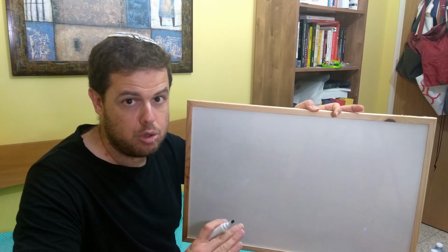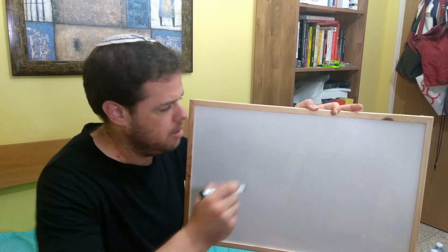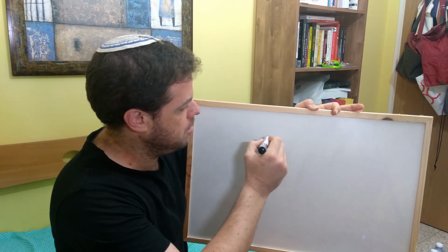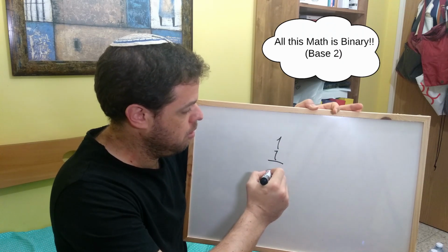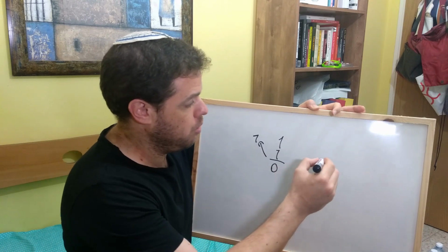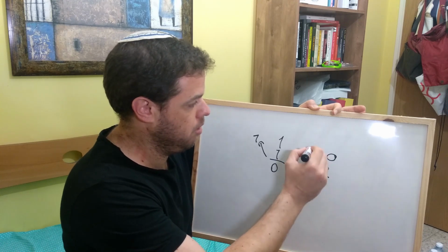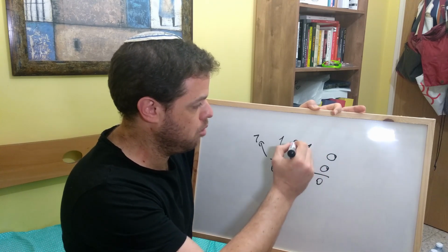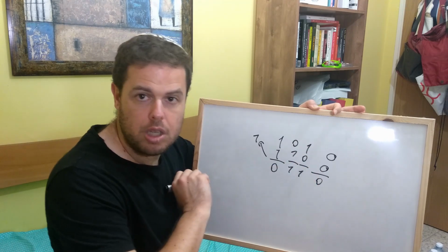With just those gates, we're going to jump ahead and fulfill the first task with hardware, with logical gates. So if we have 2 bits, 1 and 1, for example, the summary is 0 and we have 1 carry. We can enumerate all the options. 0 and 0 is 0 without a carry. 1 and 0 or 0 with 1 both have no carry, but the result is 1.